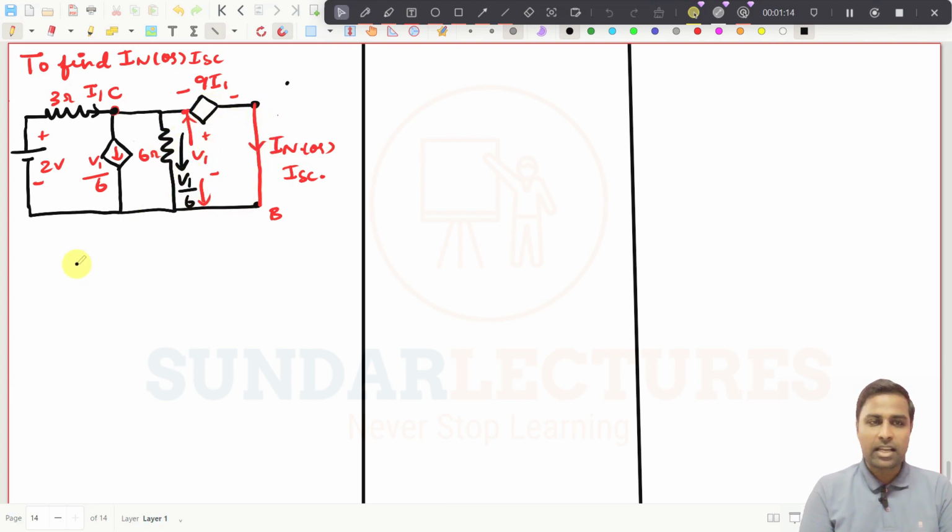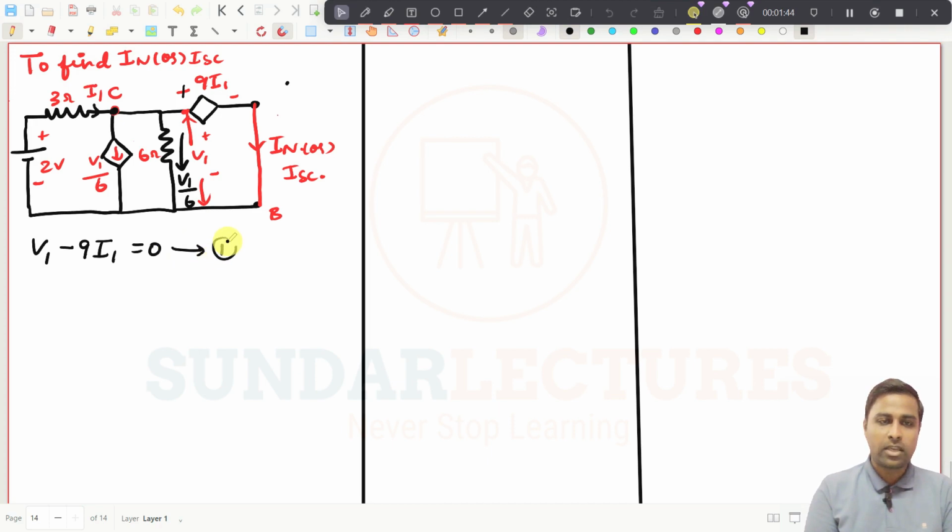If I am writing like that, from this point I will start, from minus to plus I am going, so it will be V1. And from plus to minus I am going in this voltage source, so that will be minus 9 into I1 equal to 0. That's all. This loop voltage equation has been written. So let us consider this to be equation number 1.